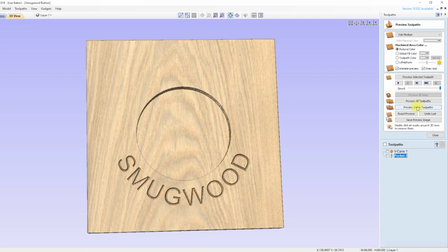So what I like to do is take a few millimetre cuts out of each hole and use a vacuum to remove the chips, and then the cutter will come back and remove a little bit more, and so on until the final depth is achieved. Using an upcut spiral causes less of a problem, but the finish isn't as good, so although it's a bit more hassle setting it up, for me it's worth it for a better finish. But for ease of the tutorial, I'll simply set the down cut to remove the material in one pass so you can see the results in the simulation, and I'll change it later to suit my machine method.